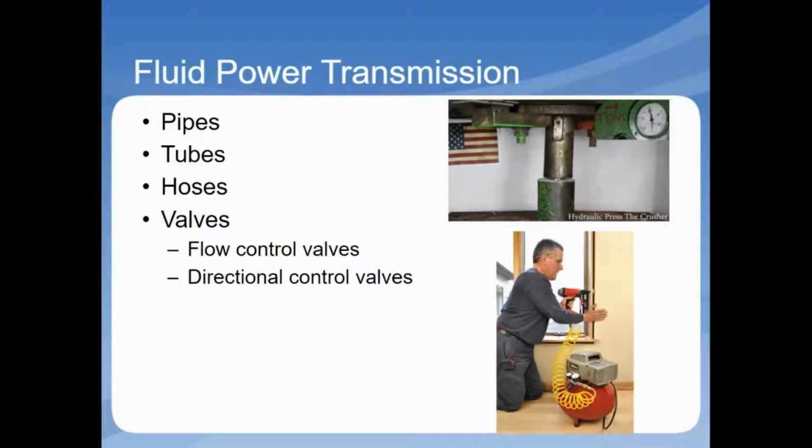In fluid power systems, fluid lines are used to transmit the fluid through the system. Common fluid lines are pipes, tubes, and hoses. The types of lines used are carefully selected depending on the type of fluid, the amount of pressure, the system temperature, and other factors. Depending on these factors, the system may use rigid steel pipes, copper or plastic tubing, or a combination of synthetic and rubber hoses. Each material and type of line has specific advantages and disadvantages that must be considered.